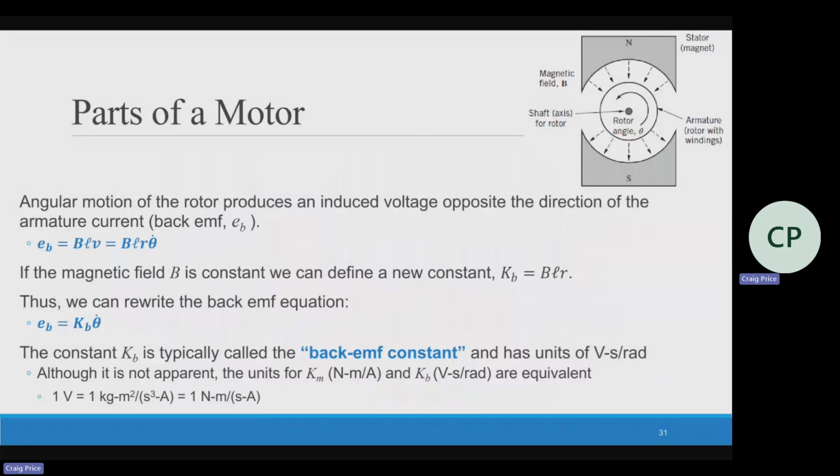At the starting of the motor, back EMF is too low, thus the armature current becomes too high, leading to the burnout of the rotor. Thus, a proper starting mechanism that controls the applied input voltage is necessary in large DC motors. One of the interesting variations of the DC motor is a universal motor, which is capable to run under both AC and DC.